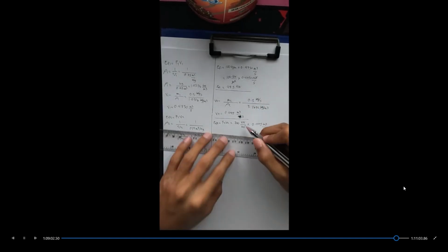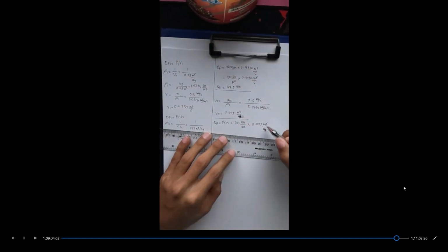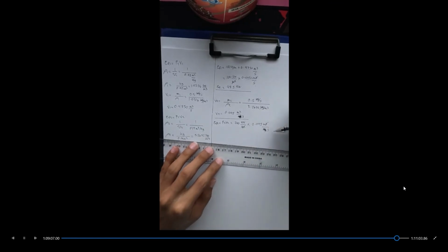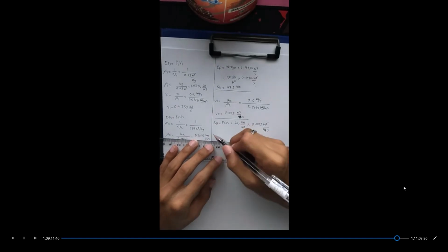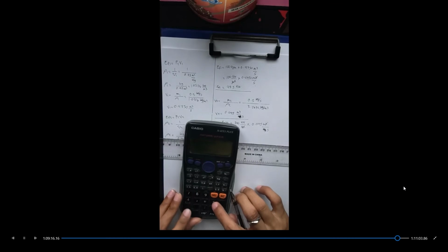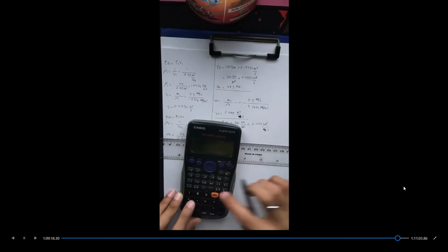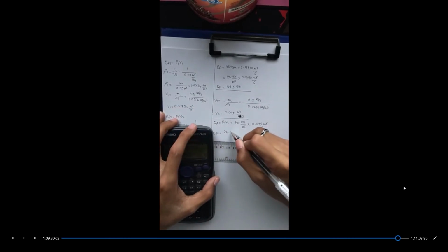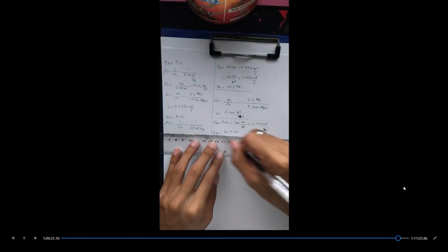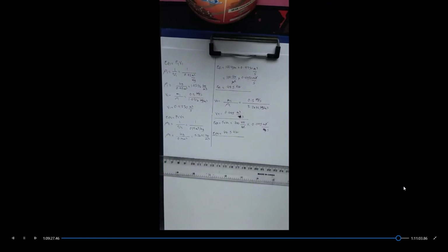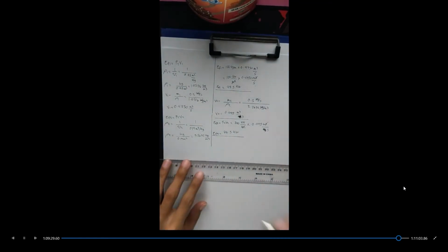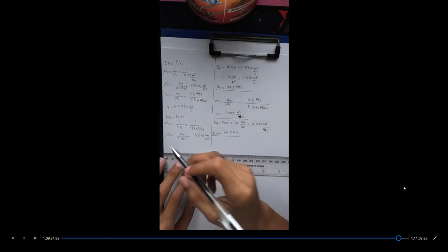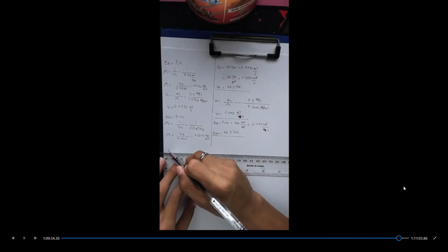So we can now cancel meter squared from the meter cube, so we'll be left with kilonewton meter per second, which is a unit of kilowatts. That means EF2 will now become 700 times 0.095, 66.5 kilowatts. Right? So we have already solved for our unknowns. Now we can use these values that we have arrived to solve for our work.